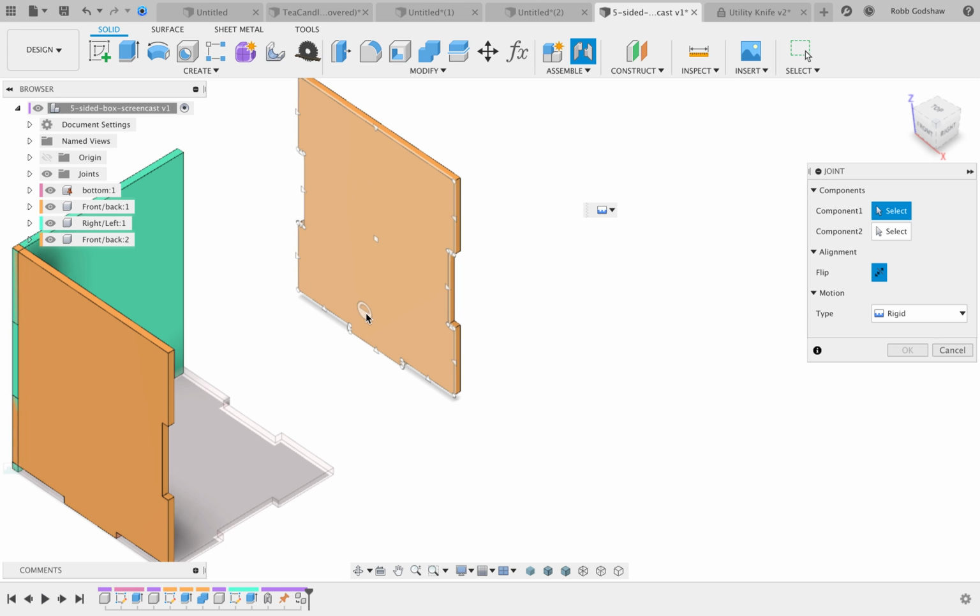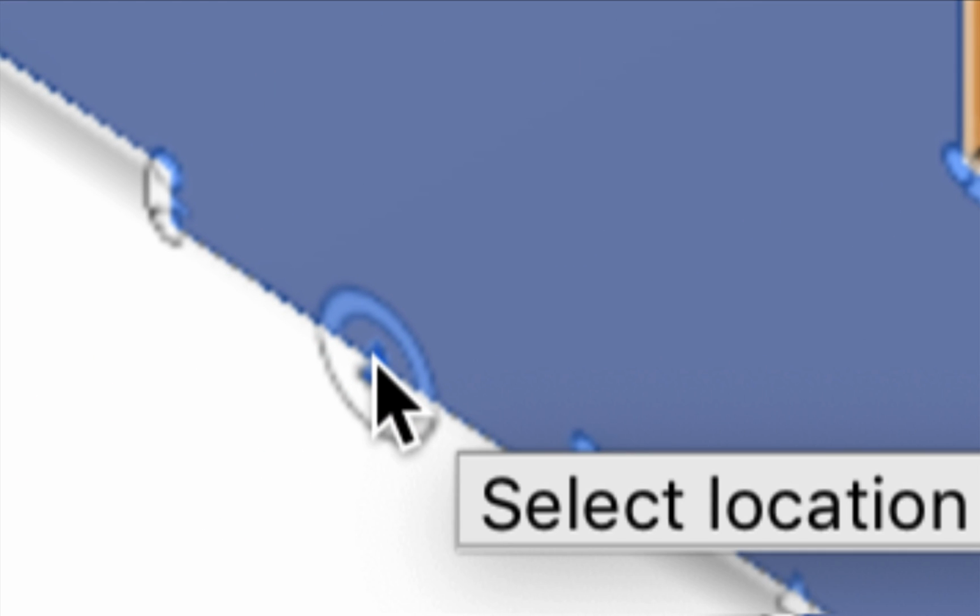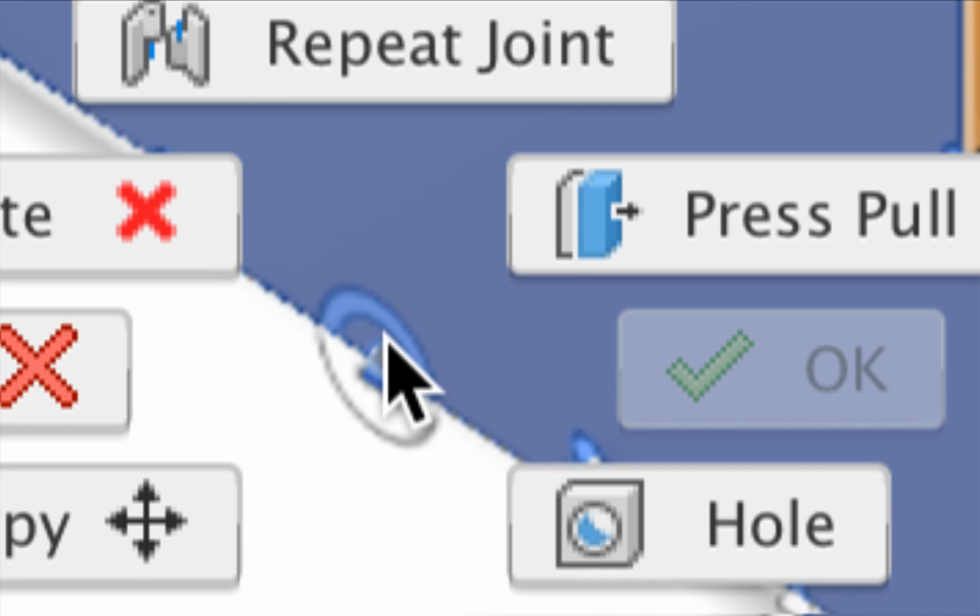You can either just click the thing that you want, but it can be kind of confusing because usually it's really ambiguous. Like, do you want that line or do you want this plane? But if you click not on a point, it will then limit your selections to things on that plane, for example. So I'm just going to do this once. I clicked the plane, X. I clicked the plane first, not on a point, just because I wanted to pick this point here. And I wanted to make sure it didn't get weird. So just click.